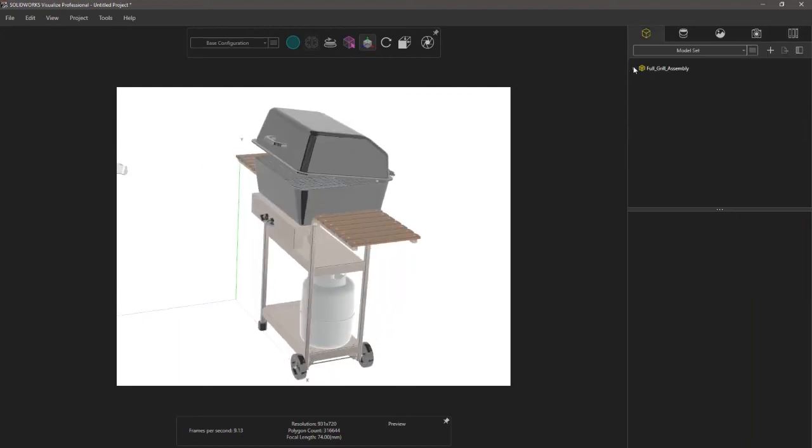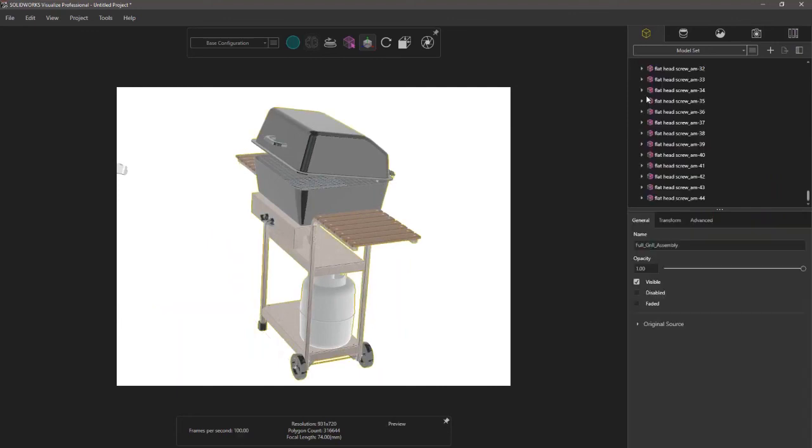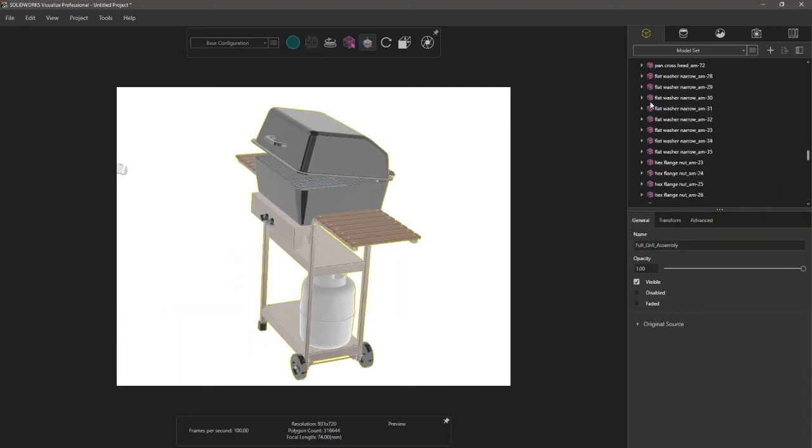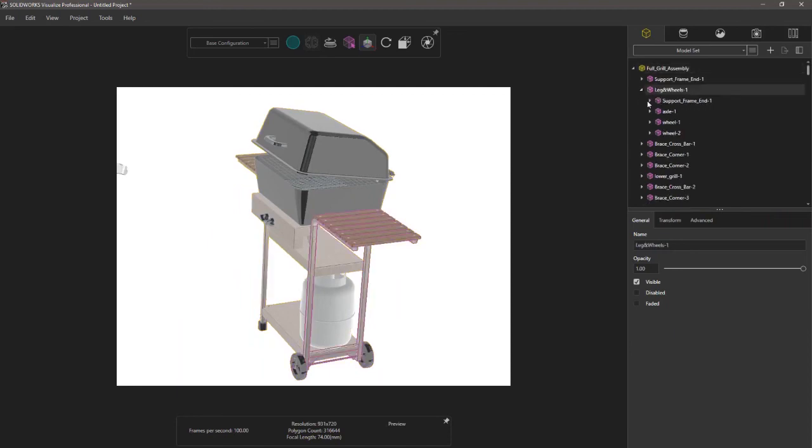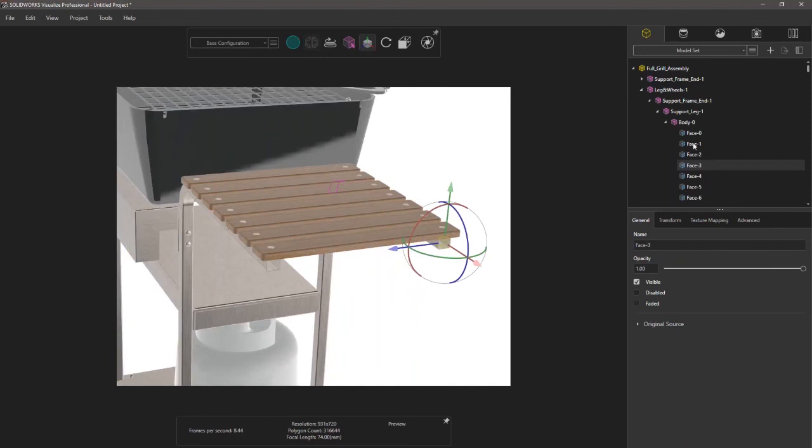And that's strictly because if we look at any of the components in here, similar to automatic mode, it brings over all the parts, except then they're all ultimately divided down into faces. There's individual faces here. I've seen people choose that option, kind of not knowing what it does, and it will really bog down performance.